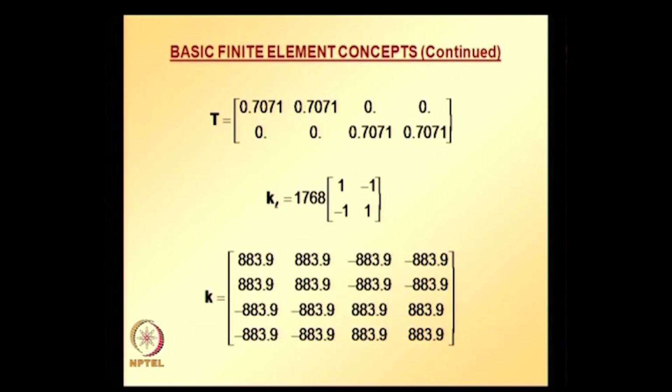And this member 1 is short by length 1/4 inch. So, the force P of T due to lack of fit we can calculate for this member as EA over L times delta L. Delta L is 1/4 inch, all are in inches. So, 1/4 is substituted, that is 0.25, and it is calculated. The value both in FPS units and SI units in kilonewtons are given there,